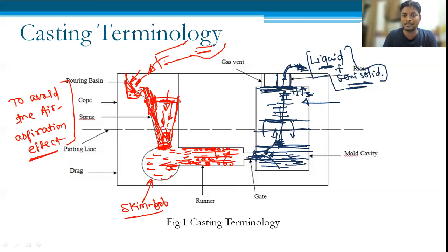So if it is starting from the boundaries, then if there is a small amount of the liquid material inside at the center line, then it is manageable. If you have to produce a number of components at the same time, once it is solidified from the boundaries, you can just take it out and use another mold. So that is also possible.